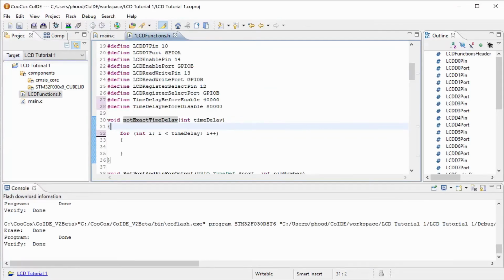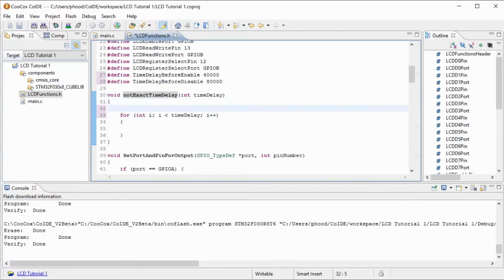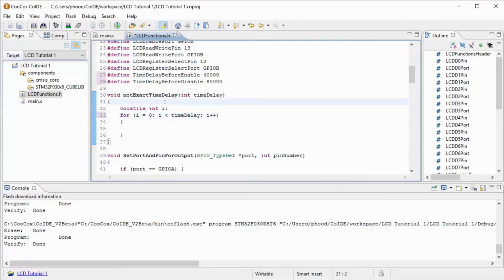I just noticed an area that might cause a problem. In my previous programs, what I would do is I would do a volatile int for the i in this for loop, because if I didn't do this, then they would optimize this whole thing out. I mean, it wouldn't actually run it, because when it does the compiling of the program, if it doesn't think that this is a changing variable throughout the program, then it won't actually use it and it'll be optimized out.